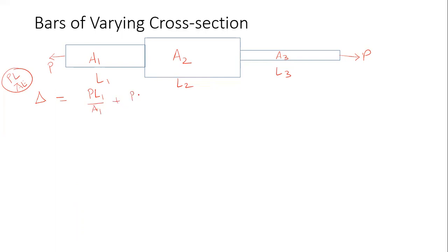plus P L2 upon A2 E, plus P L3 upon A3 E. So if the section is varying, this is how we can calculate the deformation.